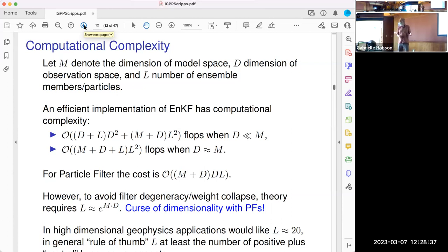They kind of generalize the real parts of eigenvalues. There's what I would call a stability spectra. They tell us about linearized stability. Okay, so the number of positive Lyapunov exponents plus the number of neutral or close to zero Lyapunov exponents. That makes things hard when we have a lot of turbulent flows and things like that, where we have a large dimensional attractor, a large number of positive Lyapunov exponents.